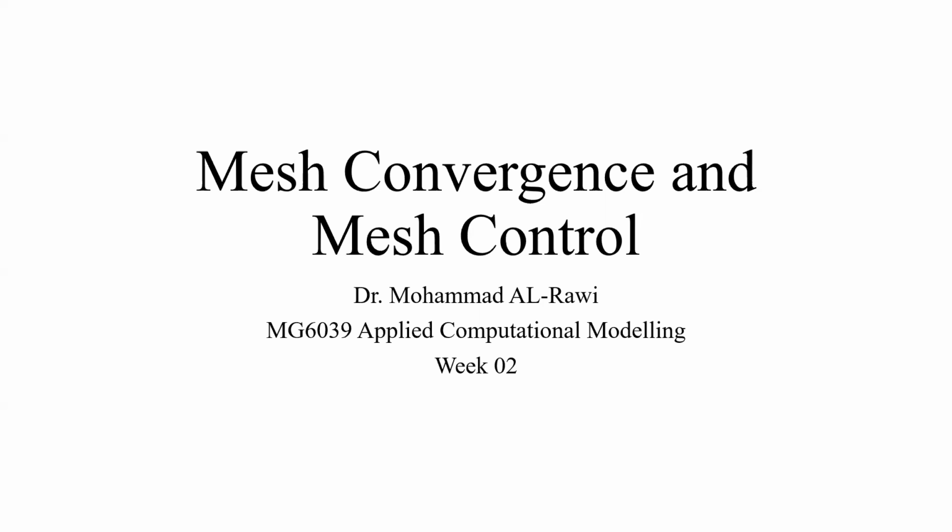So we will present the default meshing. The software already does set it up for us, and we just click run, and then we will adjust the mesh to coarse and fine mesh studies. And then we'll have a control mesh to show you how can I save my time to get the same result with less, we call it expensive computer running and time.